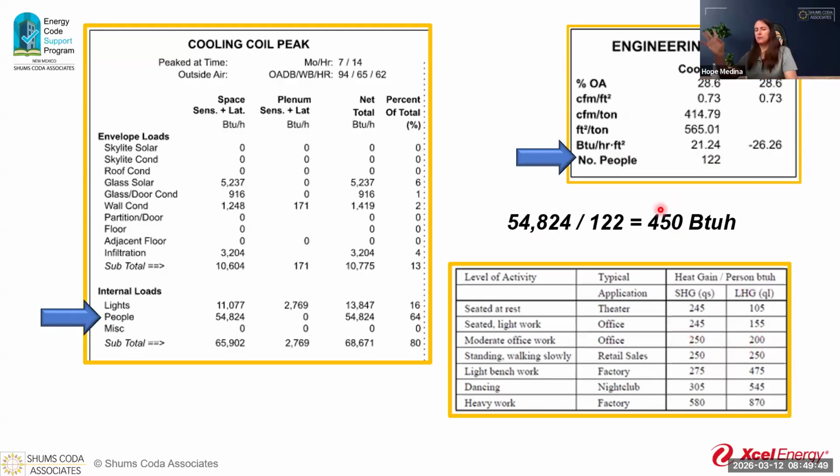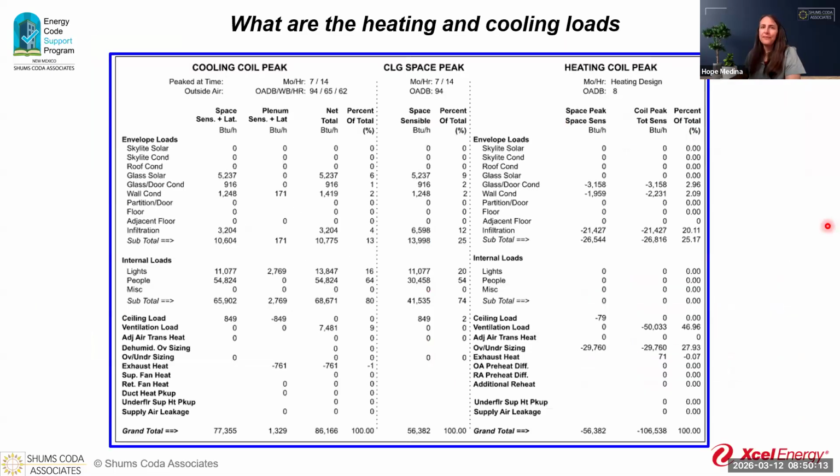So these numbers are okay. This is only if you wanted to get really, really detailed, but what I would do is check the number of people. If it said the number of people that are going to be here is 122, and then when you do your occupant load, it's 13, obviously we have a little bit of a conundrum going on here, and we probably need to get that addressed.